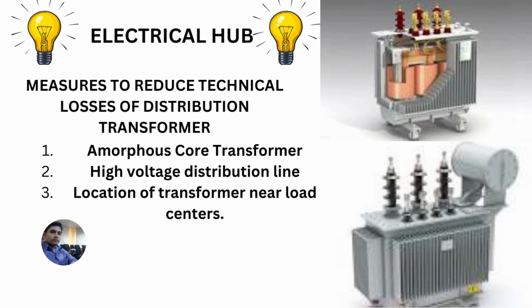Thirdly, location of the transformer near the load center. If the transformer is located very close to the load centers, the losses in the line occurring due to heat will be reduced. It can also be reduced by improving the power factor.